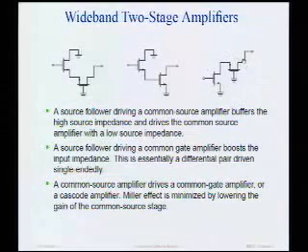And essentially, this second device is just acting as a buffer, a current buffer, and takes the current gain of the first stage and translates it to the output, and also provides some more voltage gain, which you're not getting from the first stage now. So the cascode amplifier is probably the most widely used amplifier in basically integrated circuits because it's robust, it's cheap, it's small. I can lay it out very efficiently using a shared junction, right? I don't have to have 2 junctions here. I could just use 1 junction. I can minimize the capacitance I put on my cascode node, and so it's very popular.